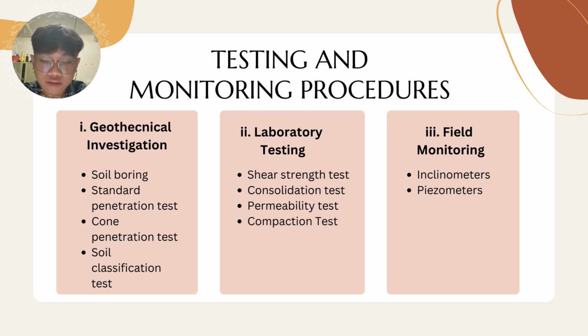The next is laboratory testing, which includes shear strength tests, consolidation tests, permeability tests, and compaction tests. Laboratory testing offers more precise and true information on the characteristics and behavior of the soil.